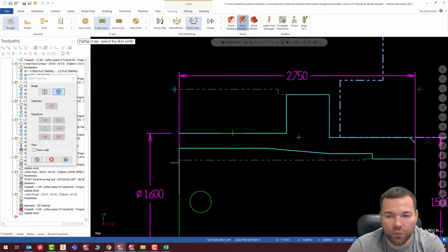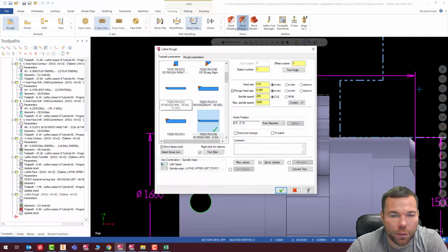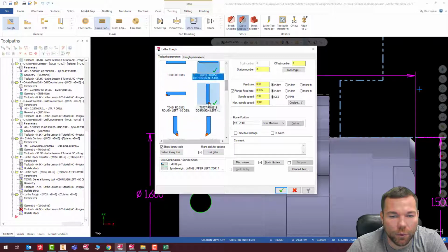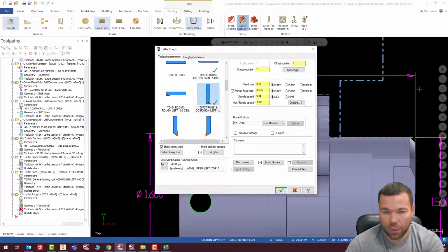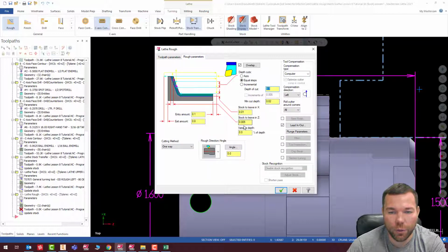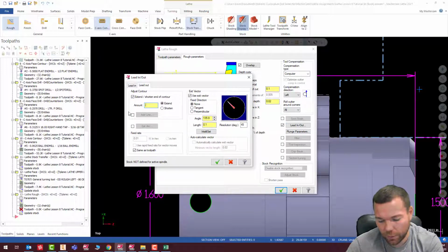Okay, so all I did was select that solid, and it automatically turned it into a profile for me. I'm going to go ahead and hit check. And of course, we're going to use that left-handed tool, wherever it's at. There it is. 900 RPMs, 3000. That looks good. All this stuff looks good. Everything here looks pretty good. Lead out, let's extend that another 0.05.